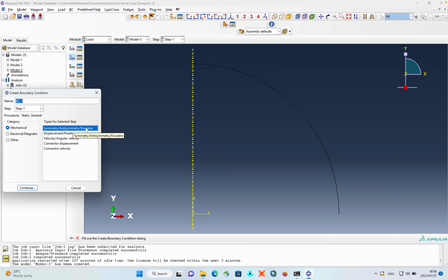So you can't get your boundary conditions or your mesh, because your mesh is where you put your elements, and your elements have nodes, and your nodes are where your forces are transmitted through. If some of your elements are terrible, then even when you do mesh convergence, it's going to diverge as well, and you're not getting any solution.